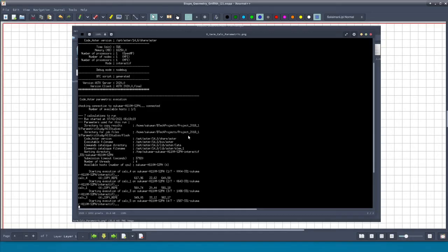For example, in this slope, I took an SRF of 1.7 and the convergence was not possible. Therefore, I took a few additional factors of safety or SRFs like 1.6 and 1.65, and after adjusting the global number of Newtonian iterations to about 12,000, which is very large, I achieved convergence at an SRF of 1.65. All right.